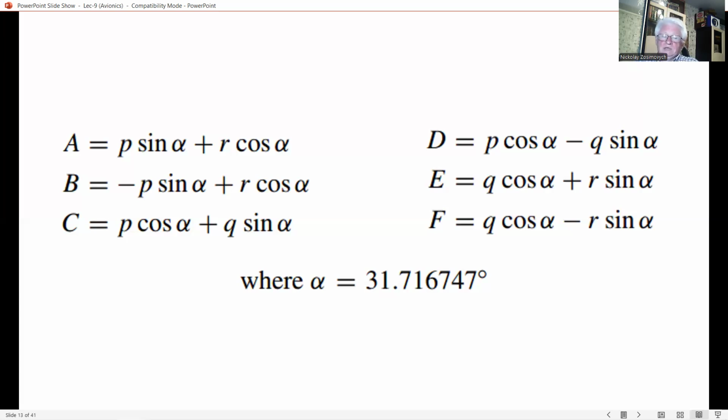For example, three orthogonal sensors with their input axes aligned with the aircraft principal axes, and four sensors with their input axes skewed at 45 degrees to the principal axes. Two such independent sensor sub-assemblies can tolerate three gyro failures.